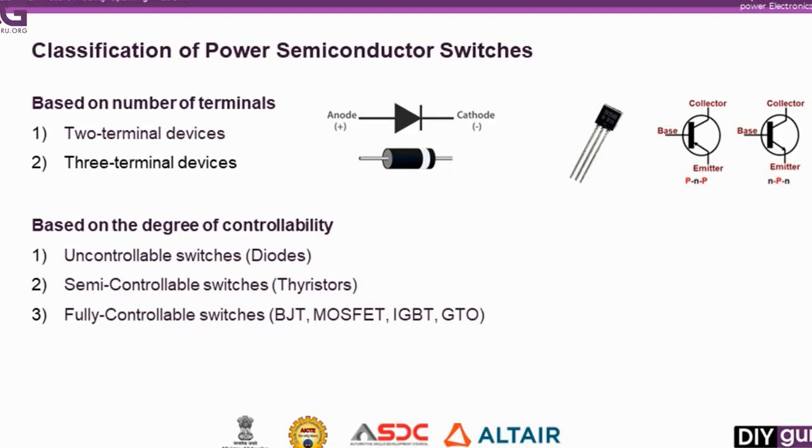The 2-terminal devices are such devices whose switch state solely depends on the externally connected circuit. The diode and diac are prime examples of the 2-terminal device categories. Now, the 3-terminal devices consist of the thyristor and the transistor. These are devices whose switching state does not solely depend on the external circuit, but it also depends on the driving signal at their respective gates.